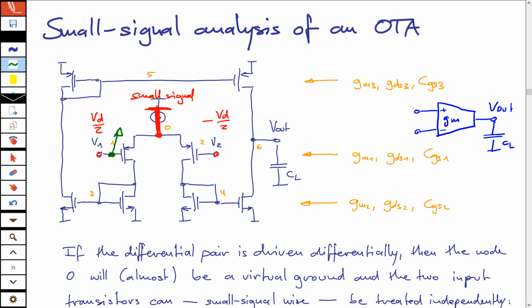What happens? If I increase this voltage, this is a PMOS transistor, so it has less voltage difference across the controlling part, so less current. And the current flows down. You have less current flowing down, so you have a minus GM in the transfer function.